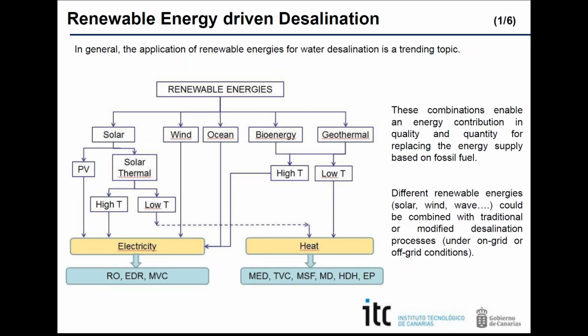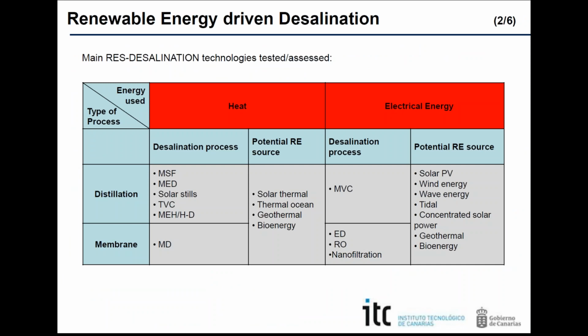In the case of membrane processes, we don't have evaporation. Membrane processes apply selective membranes, whereas evaporation uses an evaporation-condensation cycle. Here the energy to be employed is to drive pumps. This technology has advantages with respect to thermal processes. The basic ones are that the membranes operate at ambient temperature, not pressure. Pressure is a key factor here, but they operate at ambient temperature, and there is no change in phase.